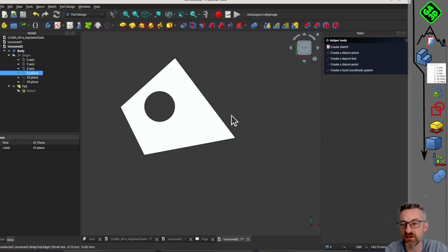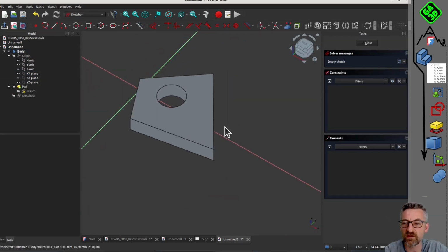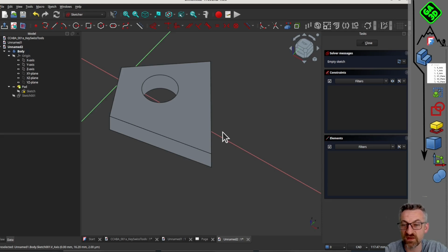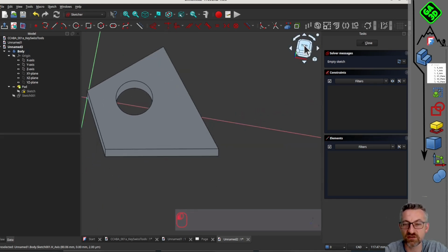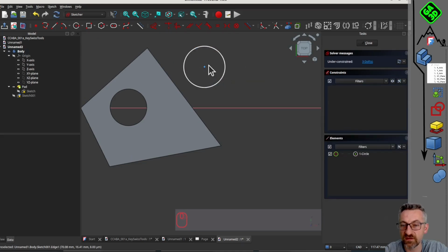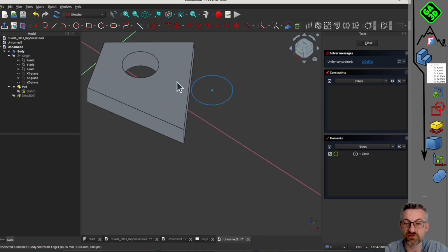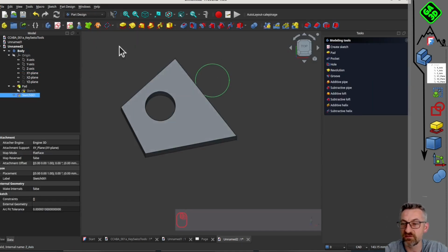So that will be useful for you as a beginner, the typical problems you might encounter. The classic beginner's mistake is if you try to do operations that don't work. There's always a reason, but a typical problem is if you try to add material and the volumes are not interconnected. Now there's an option. You could still create it with two separate volumes, but I don't recommend enabling it.